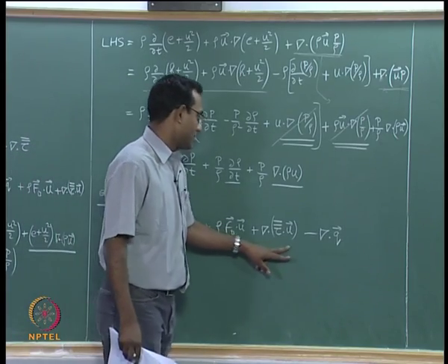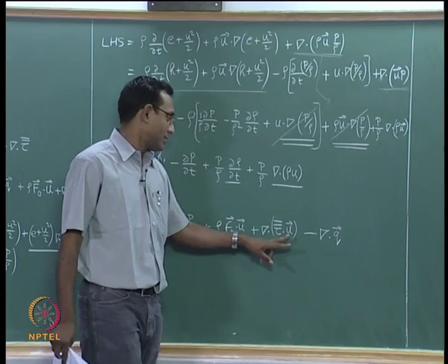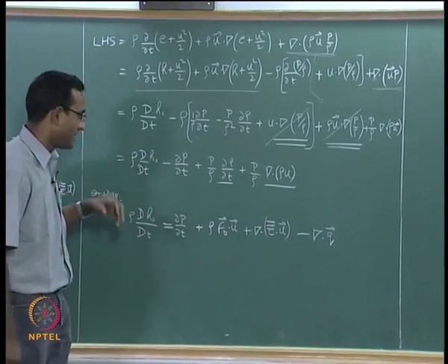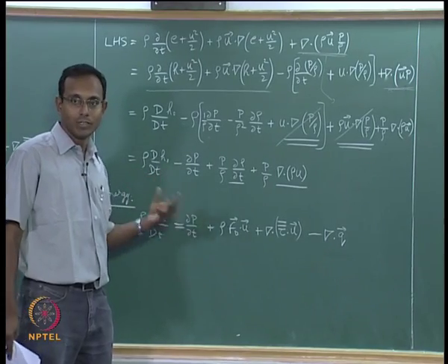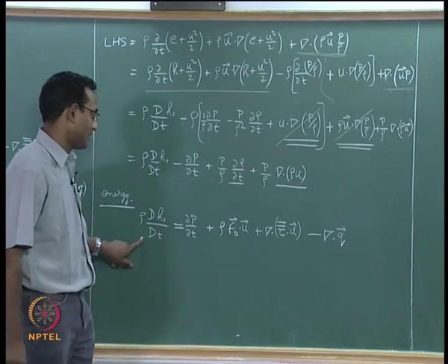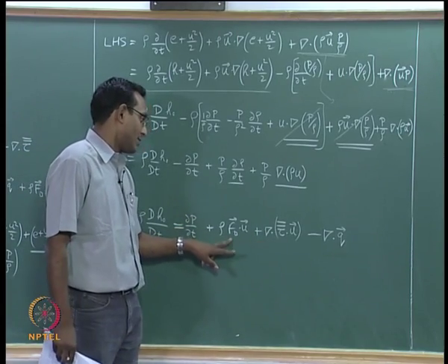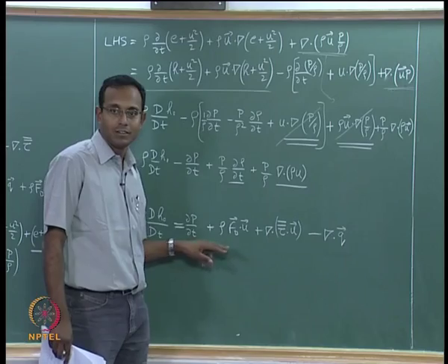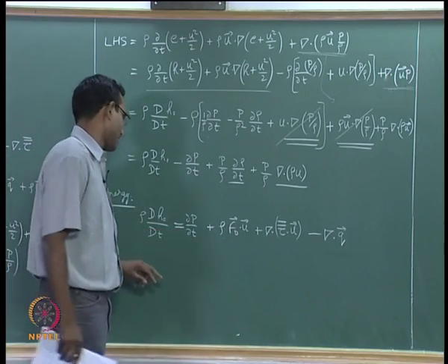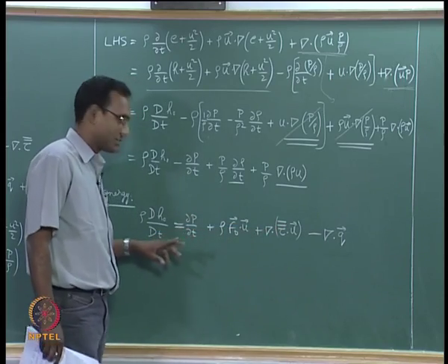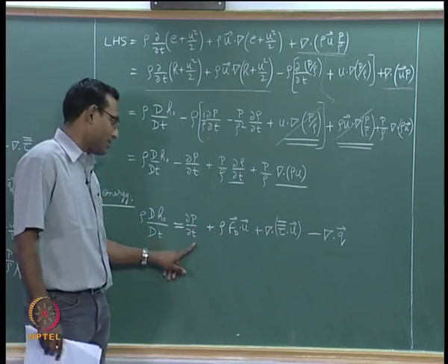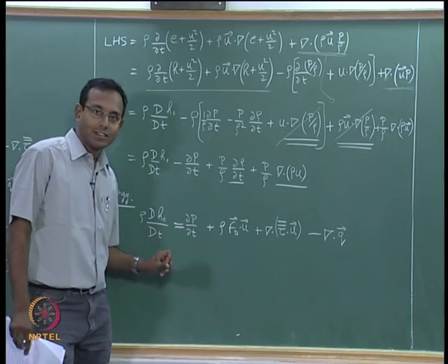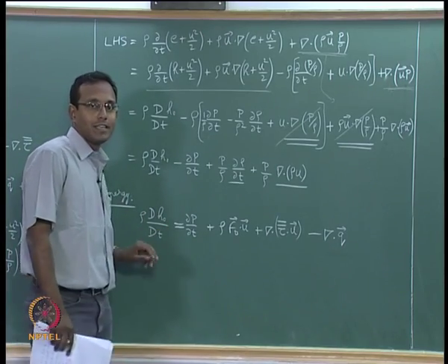The next term is here, shear stress tensor doing work with that particular fluid is going to finally generate some amount of energy, because it is increasing the energy of the system by adding work to that particular fluid, and that is this. This is the same kind of work, but done by the body force, the bulk on the bulk fluid itself, and that is given by this term, work done per unit time. Okay. Everything is in terms of per unit volume basis. And finally, there is one more term here which is talking about if I suddenly have unsteady pressure rise, that can also add energy to my fluid.